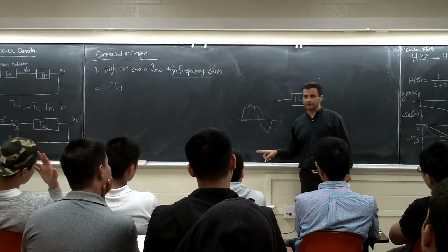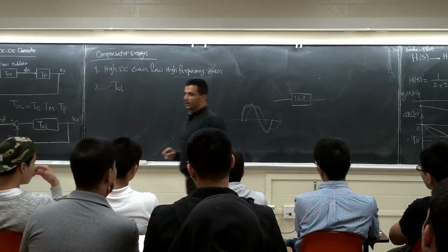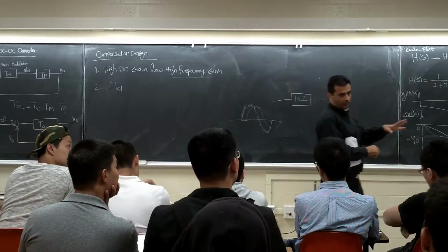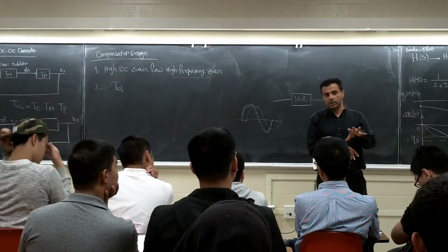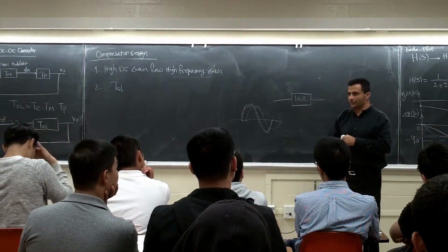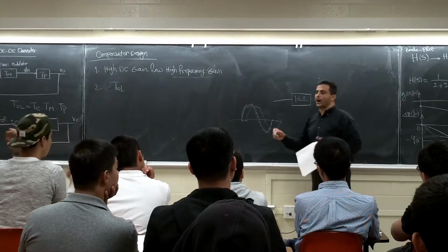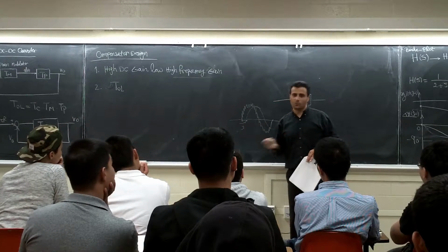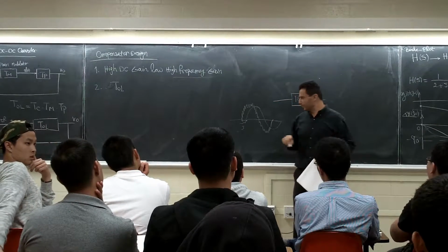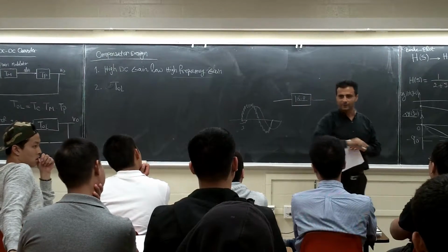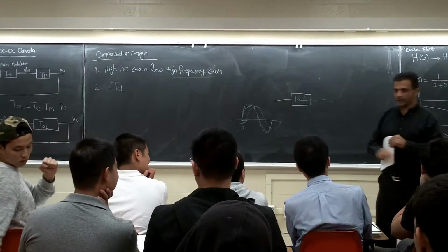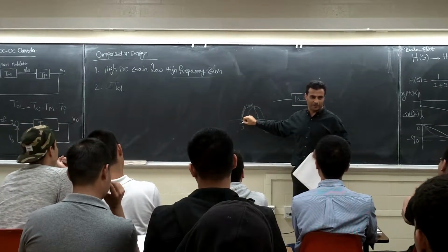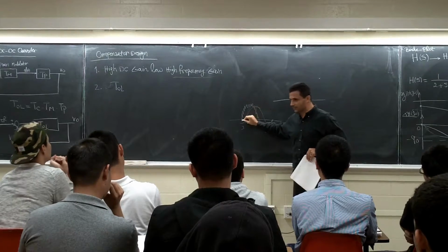The PLL we have in the company, because we have to clean up this signal, we have a filter to clean up this signal. We have to add what we call a fudge factor. We have found it out by experience. This one is about 3 degrees. Whatever we are calculating, we are subtracting, bringing 3 degrees ahead. We add that to bring it here. The problem is, this is not fixed for all the currents. It's going to be different. For example, 10 amps is here, 4 amps is here, 5 amps is here.